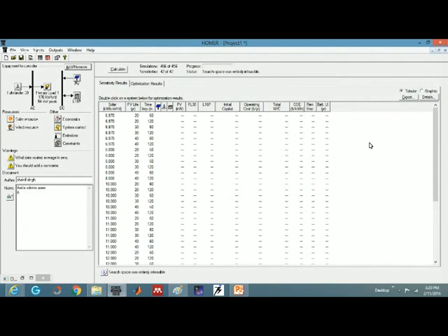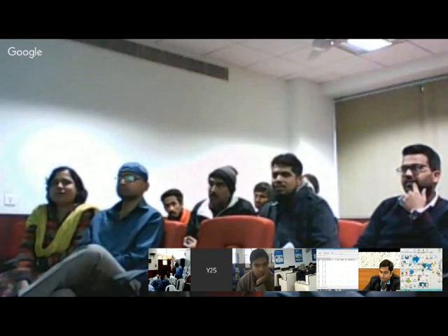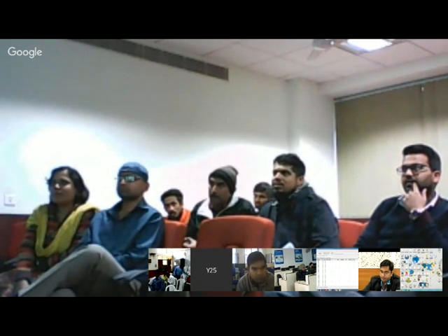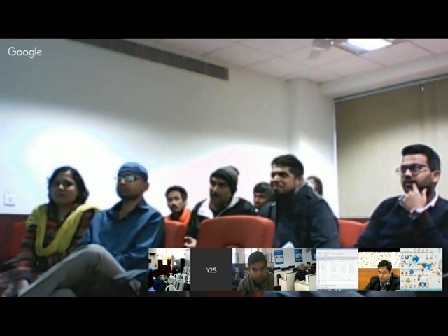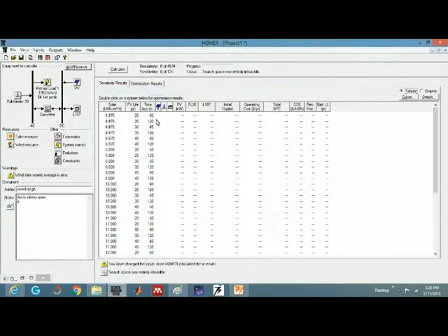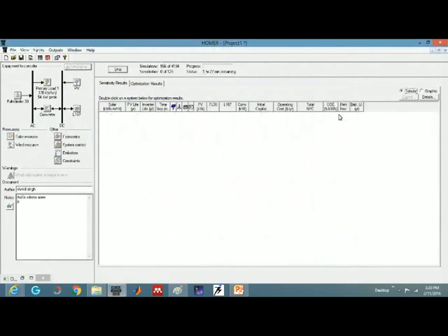Excuse me, sir. Yes. The PV and the battery bank are connected to the DC bus. Since we haven't connected any converter between the DC bus, I believe they are floating. That's why we are getting the error. Yes, absolutely right. So I have to add a converter. But before, I had not seen that part. Sorry, let's see.